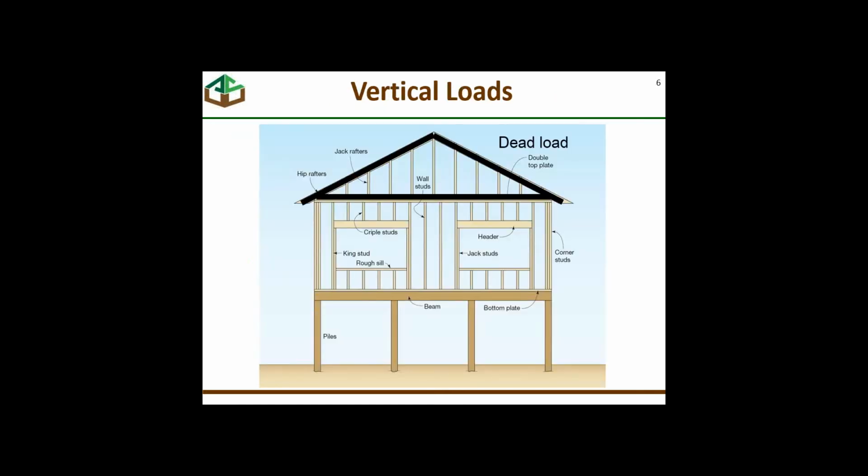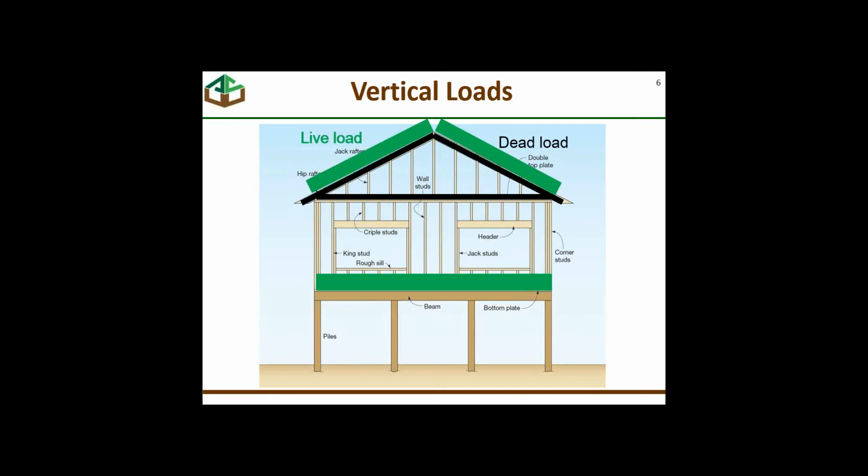So just as a reminder, we have the vertical loads on a foundation system that have to be carried to the soil through the foundation, and one certainly is dead load, and one is live load, and the live load can be obviously roof live load or live load on a floor. And then we've got wind load, and the wind load in this particular case is all showing vertical. Remember, this load is normal to the surface that it acts on.